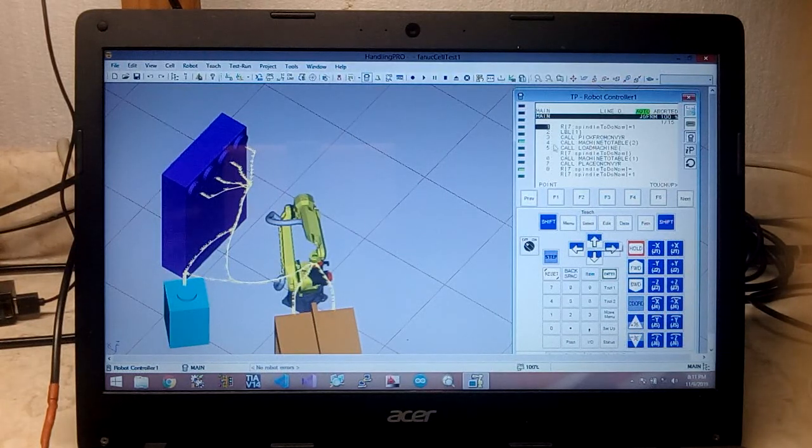And I can add another label here that will encircle everything, and that label can be tied to a background logic to which I can have a start cycle, end of cycle stop, and even add later on an auto homing feature for this. So right now they're gonna disable the teach panel. It's now disabled, and I'm gonna run this program now.